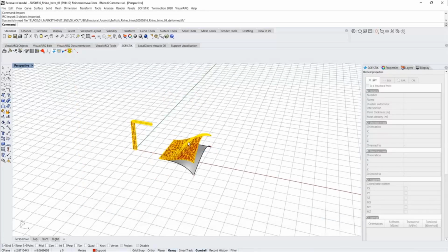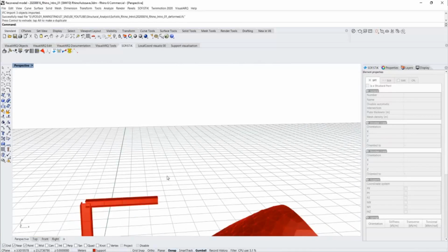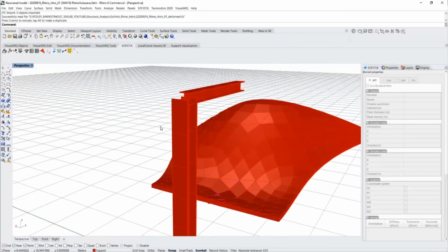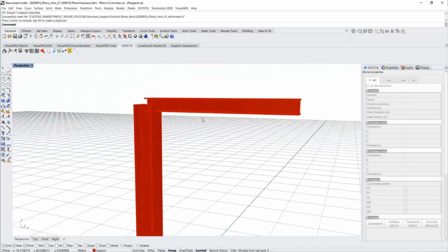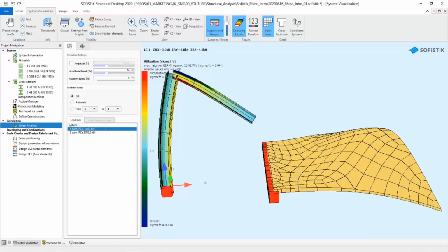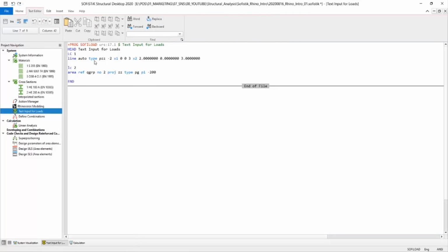This time we must be able to see the deformed structural beam position. Because the deformation is not really obvious for that load, it doesn't show much. But let's change the load case. Load unit, I'm going to give 2000 just to exaggerate.